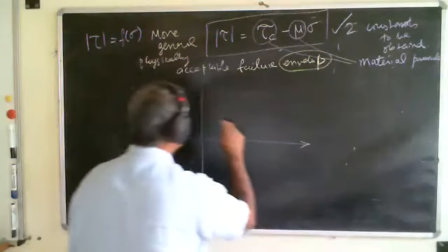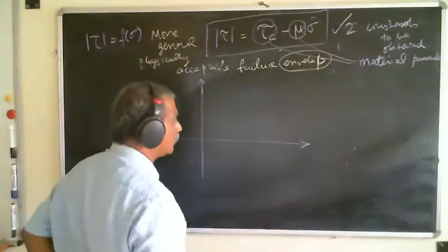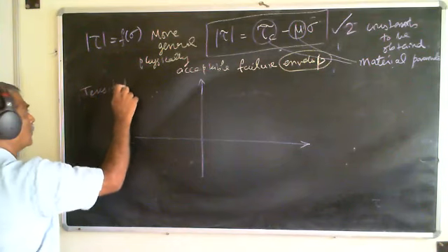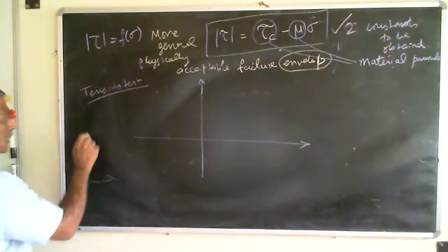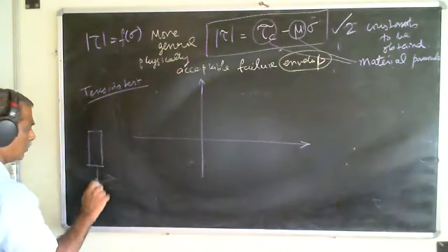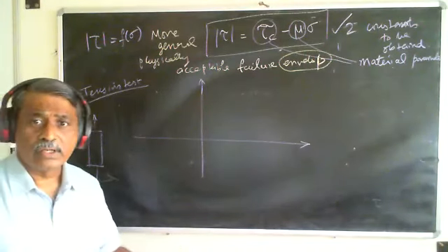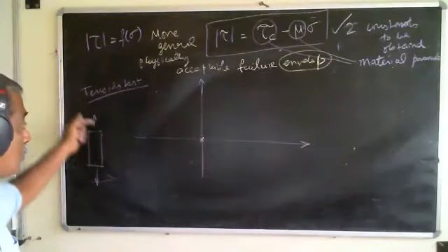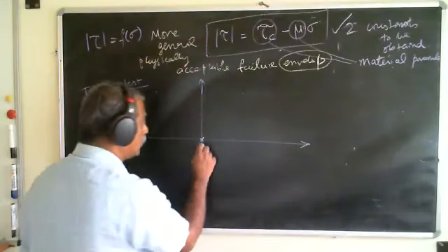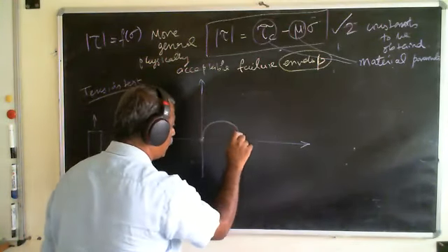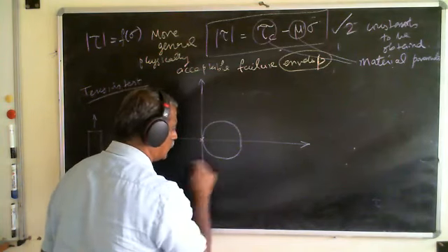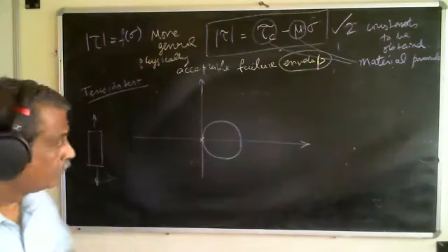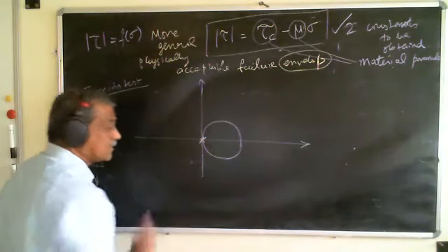I'm going to close today's discussion on that. Let's say I do a tension test. The tension test is like this, right? You already know. And how does the Mohr circle look like? The Mohr circle has to have sigma 2 equal to 0, sigma 1 is sigma, right? So it has to emanate and have a positive side circle as Mohr circle. Is this clear to you? Yeah, because one of the principal stresses is 0.